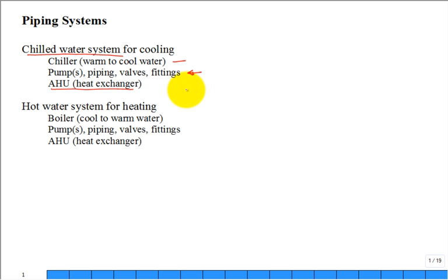If you haven't seen that or observed that, you can move a lot of energy in a pipeline. Just like hot fluid, cold fluid, it's very, very effective at moving energy. We can also put this in context of winter heating needs, and you have a hot water system. It could be steam or just simply hot water. A lot of systems move away from steam just to have a hot water loop. And so the hot water goes to the same air handling unit, different coils in it, and heats up the air and provides heating to the building. So pipes, this is how you distribute it, and these are the two ends of the process.